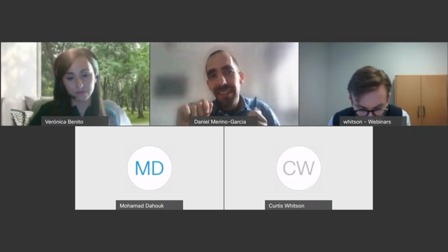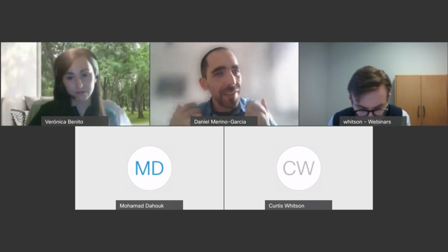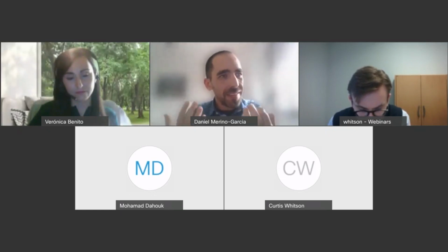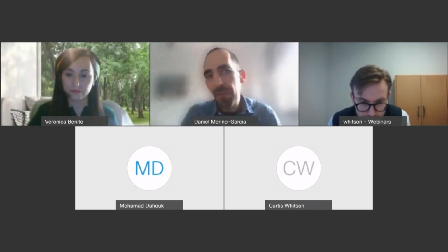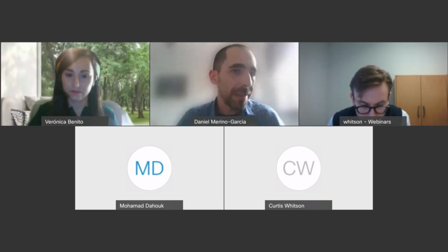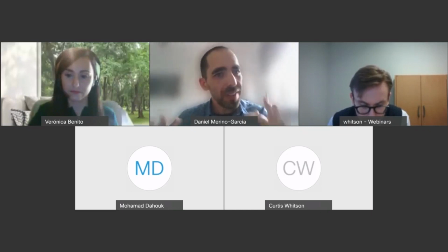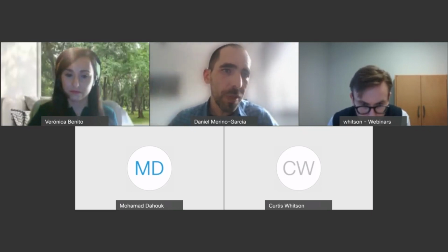If you're trying to do a unified equation of state, critical pressure will affect all of your fluids, so if you touch it, it will be for all the fluids. So composition is the only element you can play with fluid by fluid. That's where, as Veronica was explaining, knowing how much uncertainty you have in the lab, what the ranges of variability are, gives you the opportunity to play, always keeping some limits. I mentioned 5% before, and that's what we try to stick to.